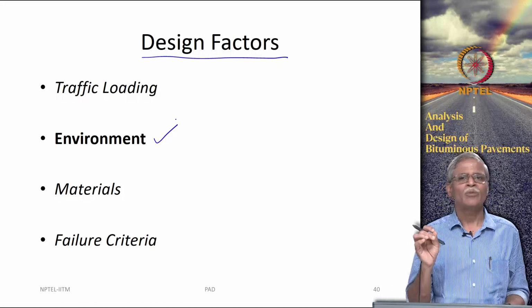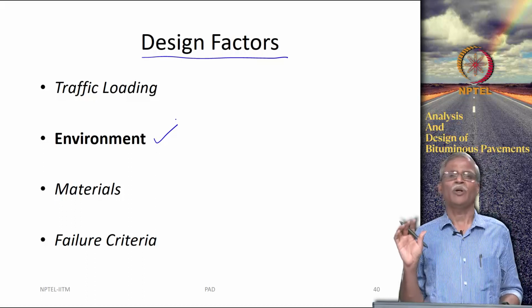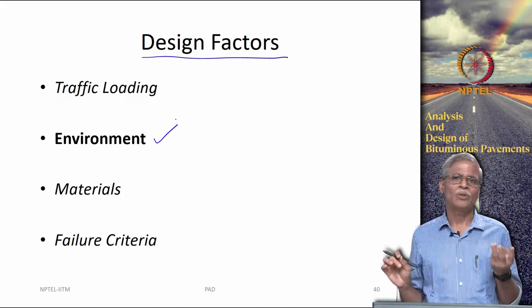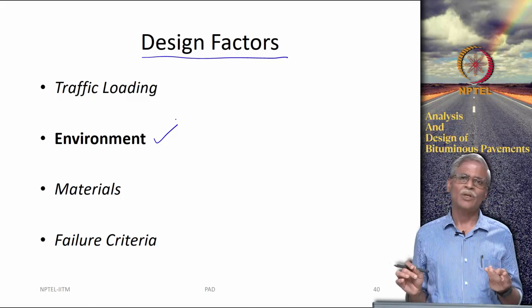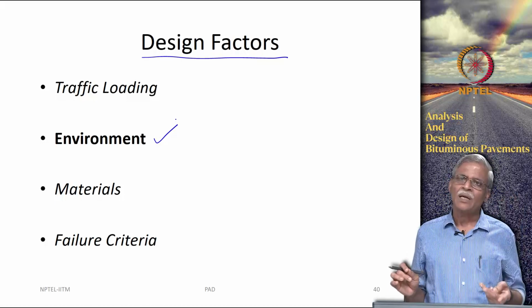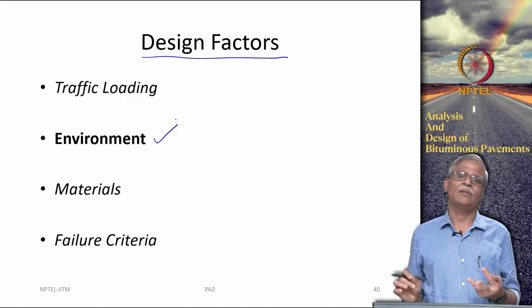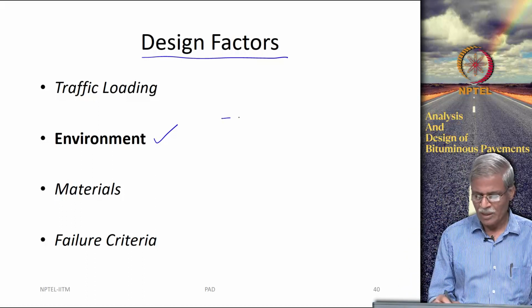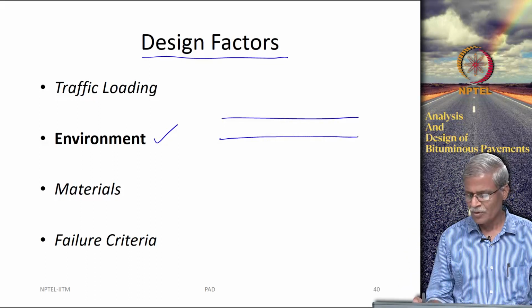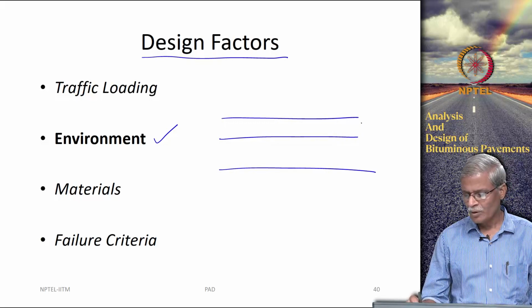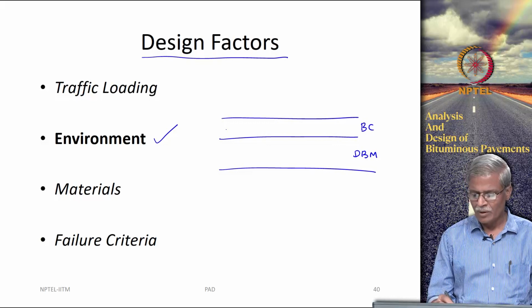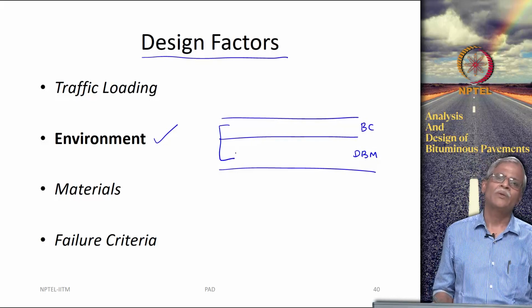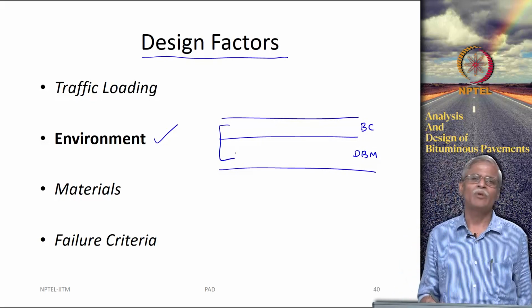sensitive when it comes to the influence of environmental conditions. This includes temperature, freeze thaw index, rainfall and many other factors. The main reason is the bituminous material that you see on the surface, your bituminous concrete, your dense bituminous macadam, are hypersensitive to the influence of temperature.